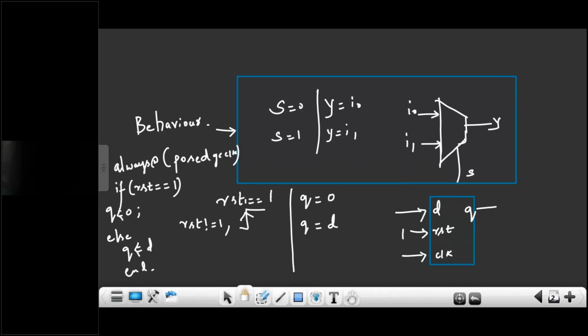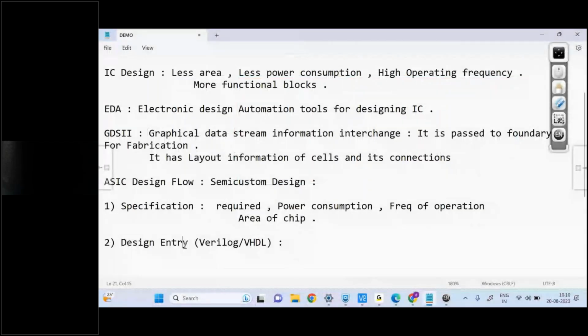If statements. So in Verilog or VHDL we have if statements, case statements, loops. Using all these things we can easily describe the behavior. So for that reason the concept of programming came into hardware also. The reason is describing the behavior is easy, right? That is why Verilog and VHDL have behavioral modeling. Many times we use only behavioral modeling. Data flow and structural are rare cases. So that is why we started using Verilog or VHDL to describe a circuit.